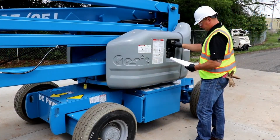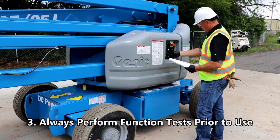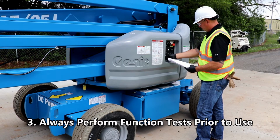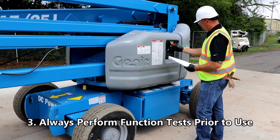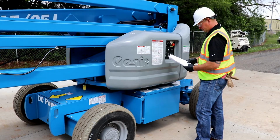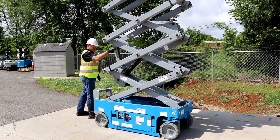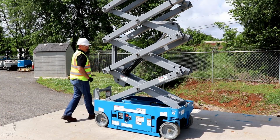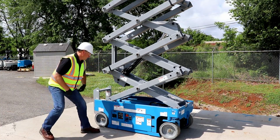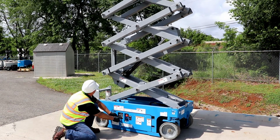If the machine checks out, you are ready to perform the function tests, our third key concept for safe machine operation. We do function tests to make sure that you can get up and down safely before you go into the work environment. We want to discover any damage, problems, or malfunctions before the machine is put into service. Of course, you have to get up in the air to do your work. But more importantly, if you have a health or safety issue and you need to get down or others need to bring you down, it is vital to verify the machine is operating properly.